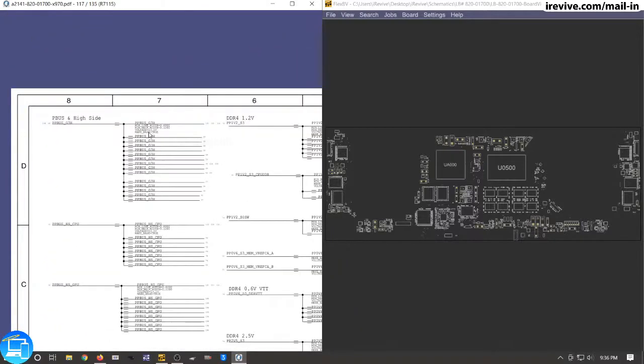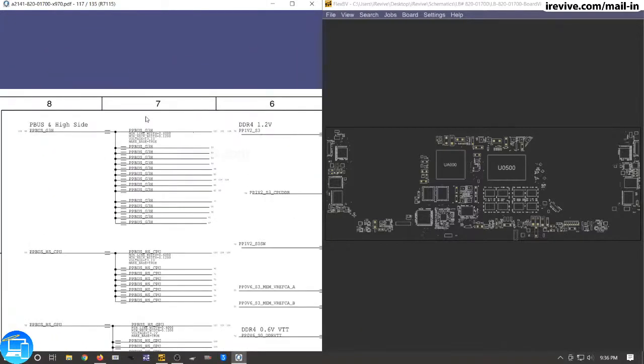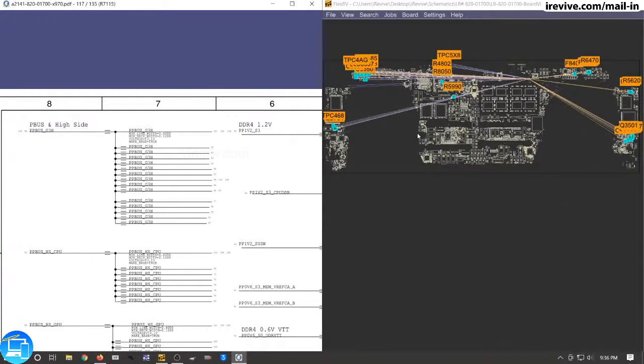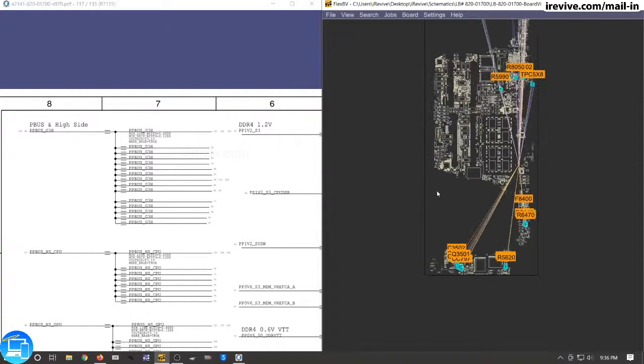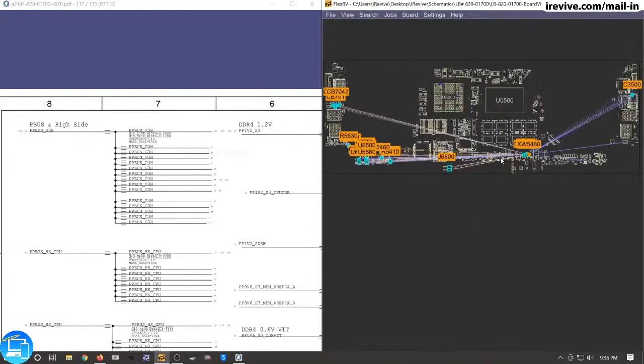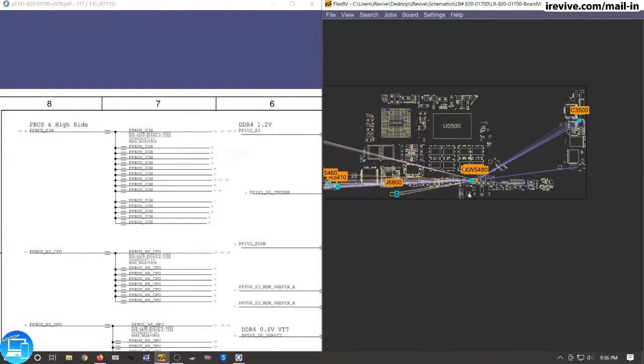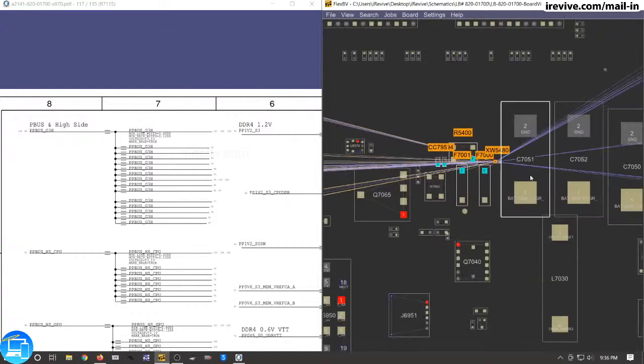All right, so first thing we want to check and see is, do we even have our PP bus present? We should have our PP3B3 present because that's how we have our 20 volts coming from our CD3215s. I think this one has CD3215s. I don't think they switched them into CD3217s on this model yet. I was wrong. This one does have CD3217s. Alright, so let's take a look over here at these fuses at our PP bus.